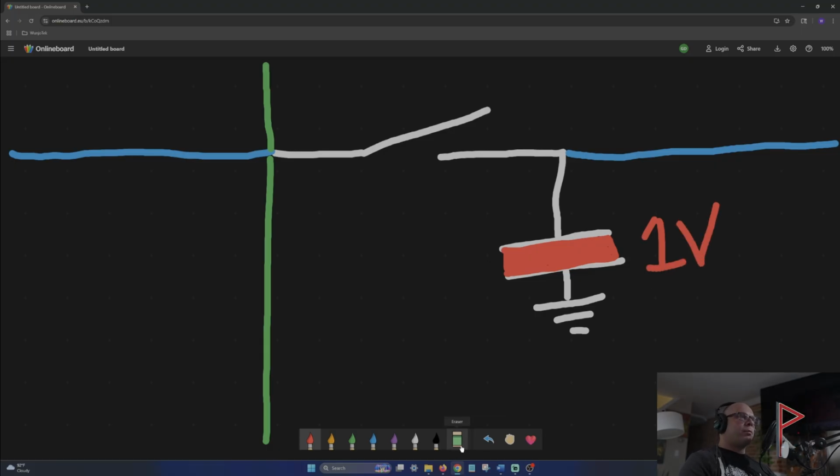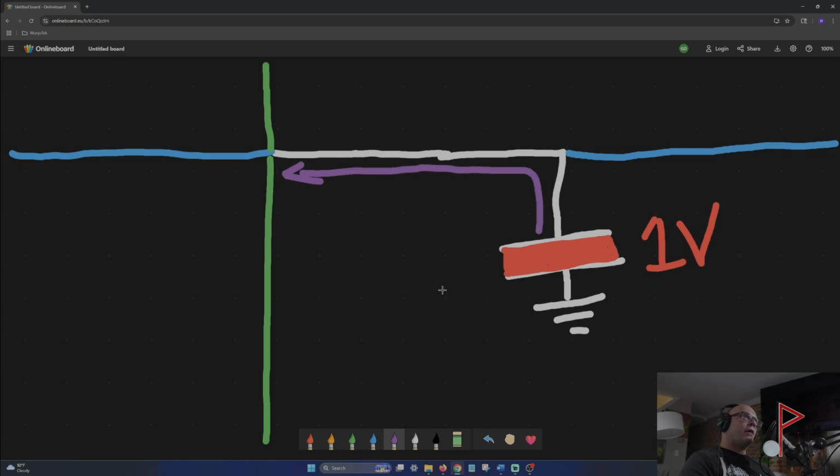But at this point, the word line is asserted, which means that this transistor is closed. This voltage then is now flowing from the capacitor over to the bit line. Now, the first step in reading, writing, and refreshing, and that's what we're really talking about here, refreshing, because I'm explaining tREFI, the first step